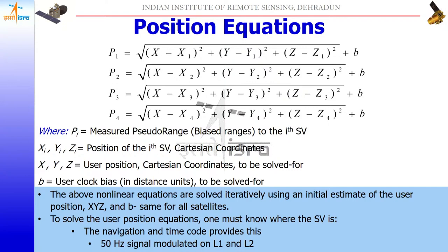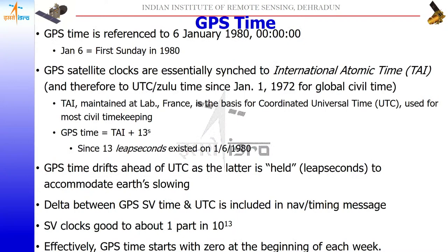There are 5 Keplerian elements, and you have to estimate all those Keplerian elements with the help of the ephemeris, so that you can provide the different error budgets related to the rotation of the earth, the flattening, the shape of the earth, the datum. The ephemeris helps in providing all these estimates, and the mean anomaly, all of which are estimated with the help of that.